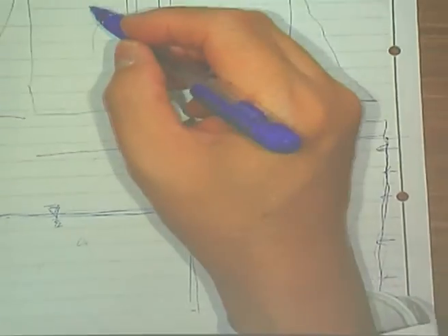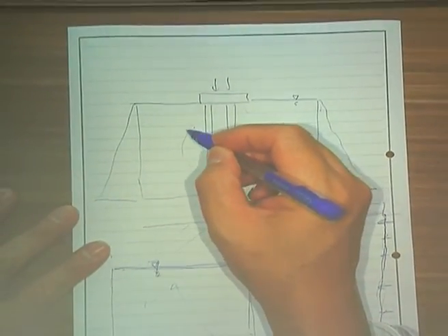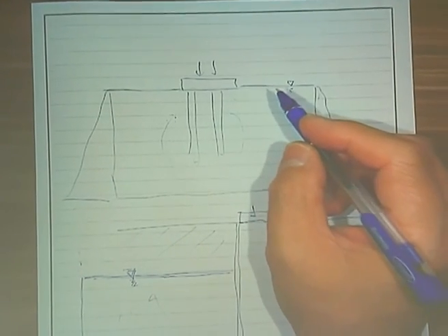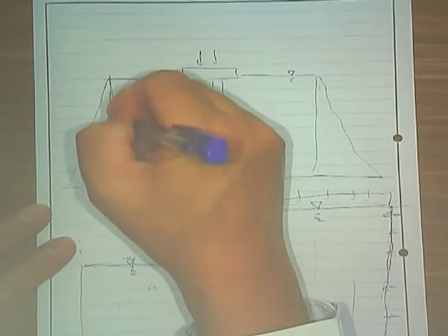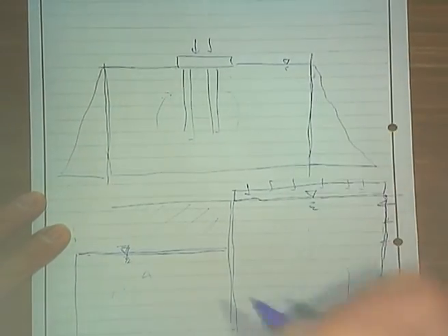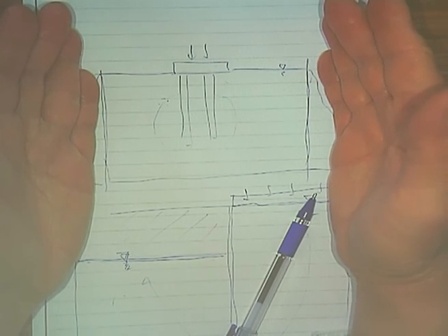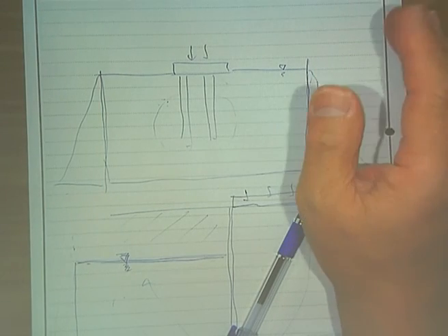Oh, undrained condition, you don't need to worry about pore pressure condition. You see, the assumption in undrained condition, let's say we take this problem, is that the water is not flowing from here to here or anywhere. There's no flow of water relative to the soil. So most programs don't even ask you for a boundary condition. This is assumed to be closed, the water cannot come out, cannot go in. The boundary condition is irrelevant.